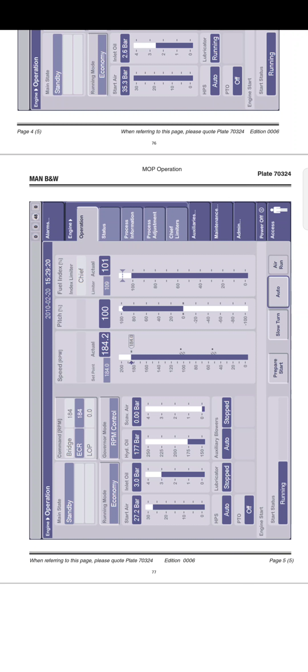So the set point and the actual running speed of the engine are shown in the two displays above the graph. The uppermost display is the speed command modifier. The speed modifier is a function that may override the actual speed command and control the speed system set point for the engine speed. When the function is active, the control mode is shown in the speed indicator.